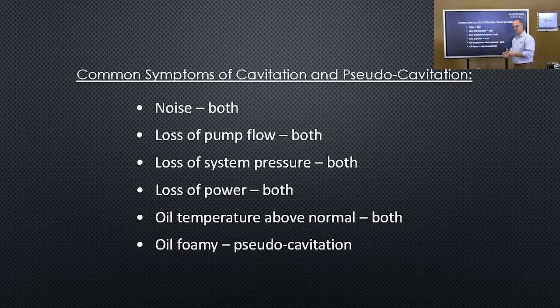What's happening is I've got an infeed of air to the intake of the pump that is coming in through a low oil level, through a cracked connector, etc. If I'm adding air, which is turning my pump into a semi-oil pump air compressor, then obviously I'm going to pump air into my system, and this is going to aerate my entire hydraulic system. This is very bad.